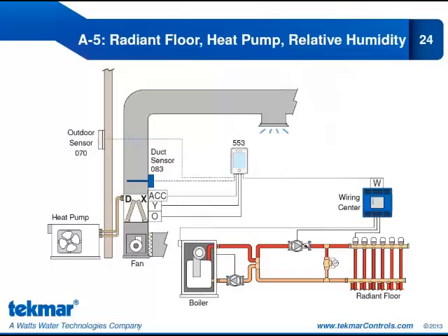Our fifth application is also our first heat pump application. So this is a radiant floor with heat pump and relative humidity. Remember, when the title says relative humidity, that's because we can control a humidifier or a dehumidifier. So first stage of heat, the radiant floor, we see the W going to the wiring center.